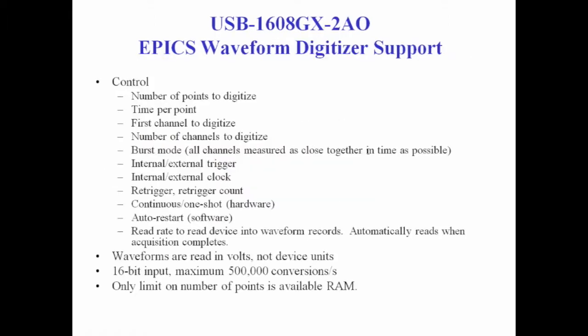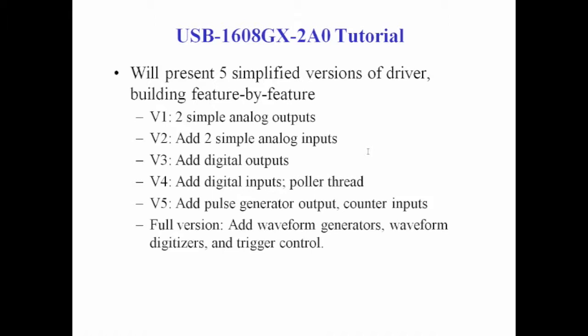It's got a waveform digitizer where you can control the number of points to digitize and the time per point and the number of channels. And it has a burst mode where you sample all the channels as close together in time as possible. Different kinds of triggers. You can have it be continuous or one shot. And again, that's the same pretty generous limitations on number of samples and so on.